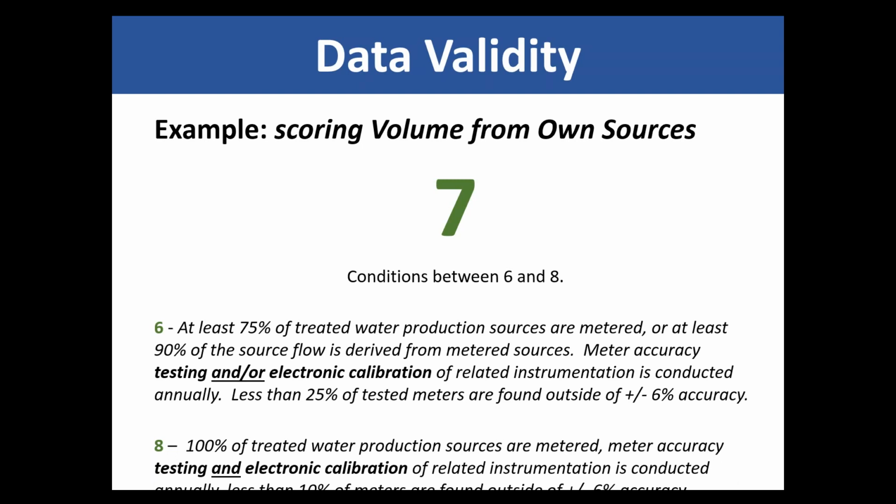But I think also to appreciate here, right, the requirements to meet a data validity grade of 8 that you calibrate and test. For some utilities, that might not be attainable, given installation conditions of the meters, that there's just no way of testing the meter. All I can do is calibrate the meter, but I cannot test it unless I go into some capital projects and dig up downstream and put a comparative meter then in there or a tap or whatever. So those are the realities. It doesn't mean because you don't meet an 8 that's a bad thing. It's just reflecting where you are.